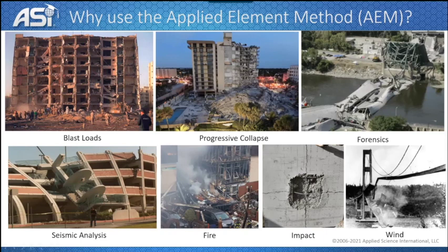Also, with forensic engineering, if you have a case like what we see in front of us here, the I-35 bridge, and you want to investigate why this bridge experienced a collapse, this is also a very good application for the applied element method. The seismic analysis, either for a new building or an existing building: the technology has the ability to do time history nonlinear dynamic analysis, where you assign the earthquake that you are going to design your building for, and you can see the effect that will happen in your structure,